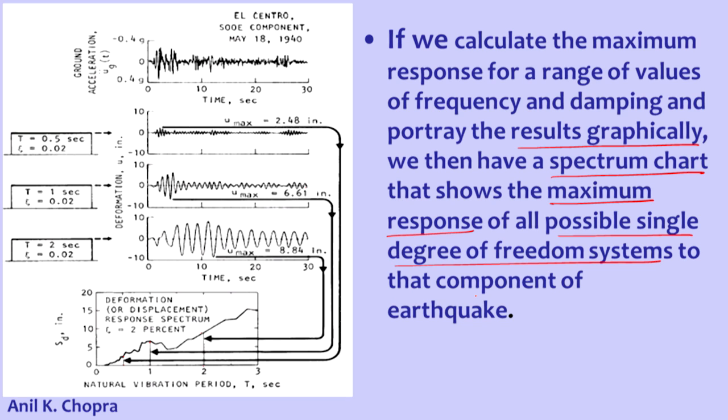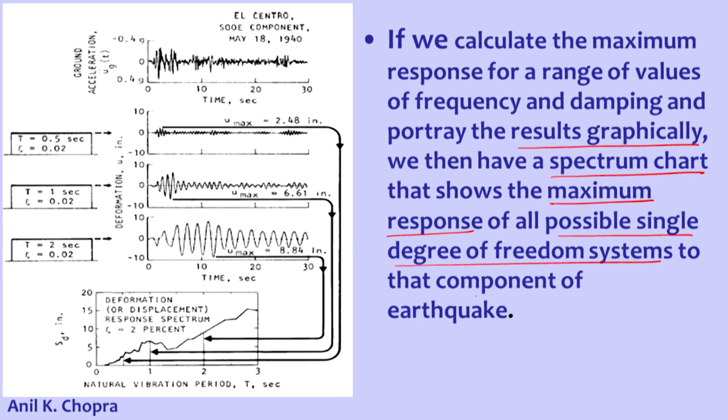Now once we have this kind of response spectrum developed for an area, then in that area whatever kind of building is coming, say single story building, 2-story building, 3-story, 20-story building, 30-story building, before design of that building itself, we can calculate the natural period of that building, put it on the x-axis and check the maximum displacement value.